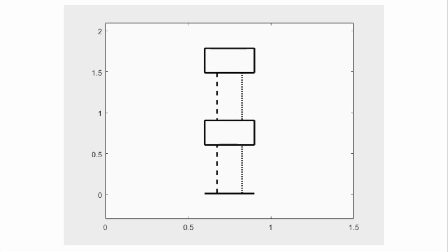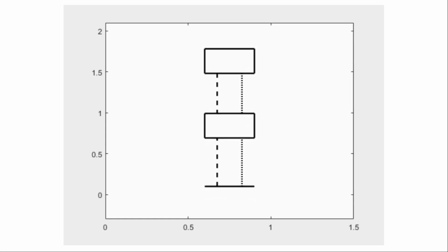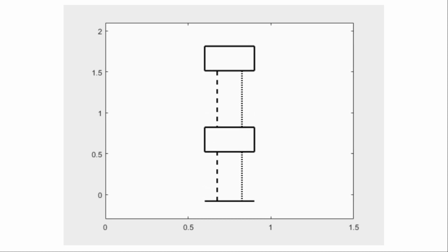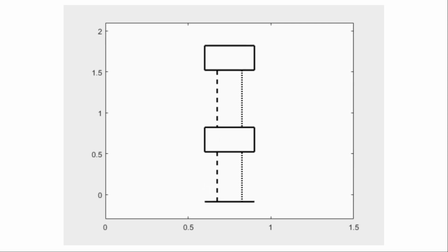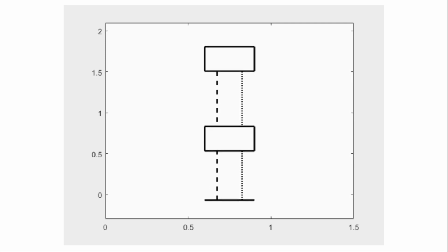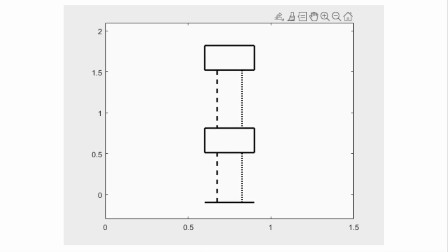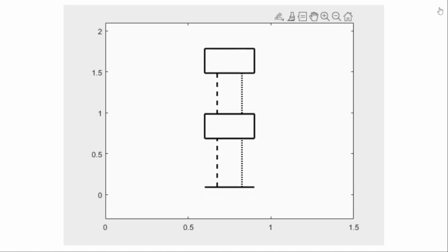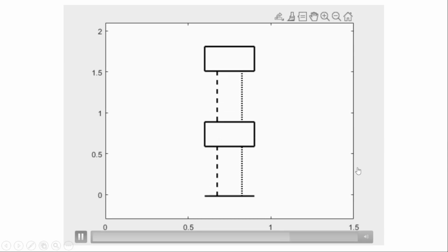We see that it is not transferring much of the vibrations to the car body, so the car body does not move up and down much, although the tires are actually moving up and down quite significantly. So this is how we would want the suspension to behave ideally.